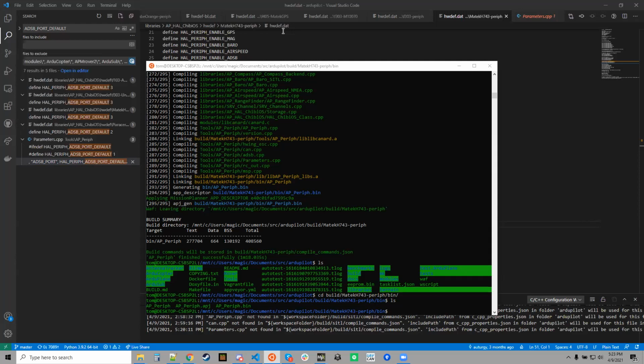One thing we have done recently is we now log the firmware string and firmware version of every CAN device that ArduPilot sees on the bus. We log that in the onboard log, and we can optionally send that over MAVLink as well, which is quite handy. It's the new CAND message, CAN device message, in the log. That at least allows you to tell whether your devices are up to date by what firmware they're running. But the next step of having an automatic update of the nodes, I think, is essential for much more widespread and easier adoption of CAN devices.